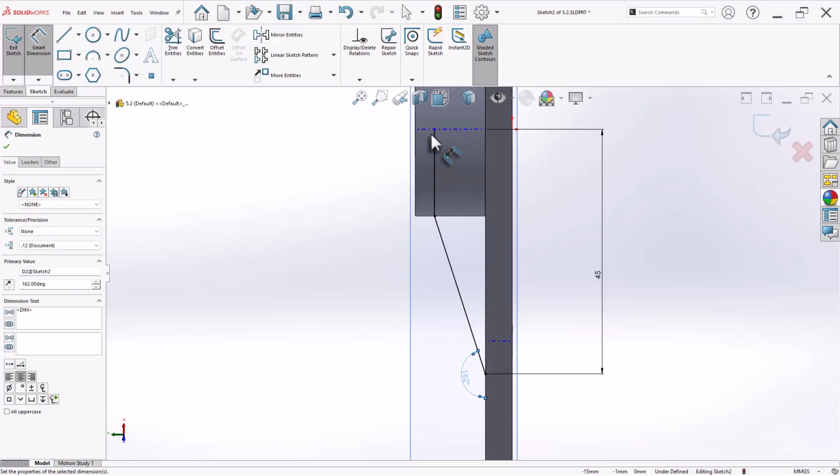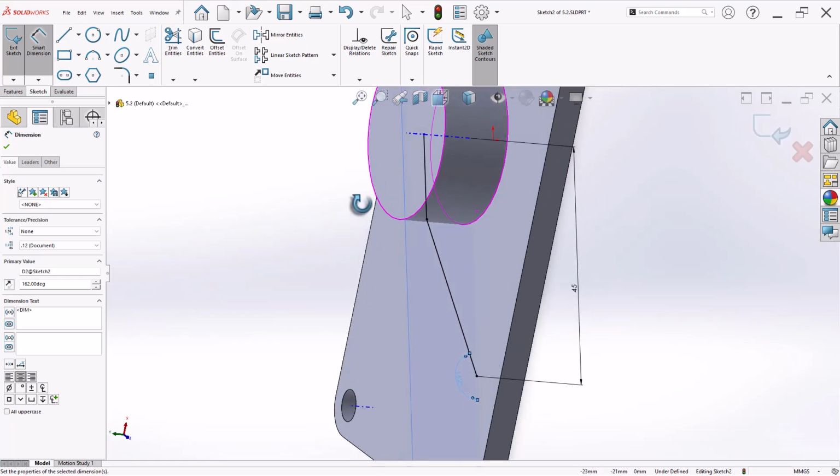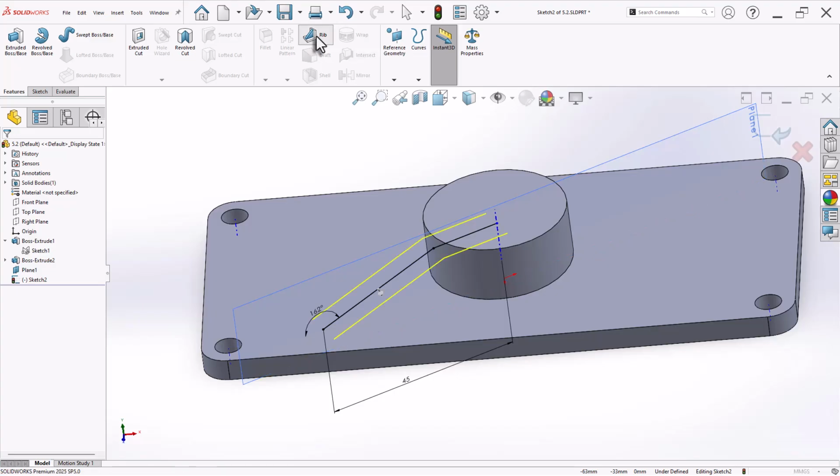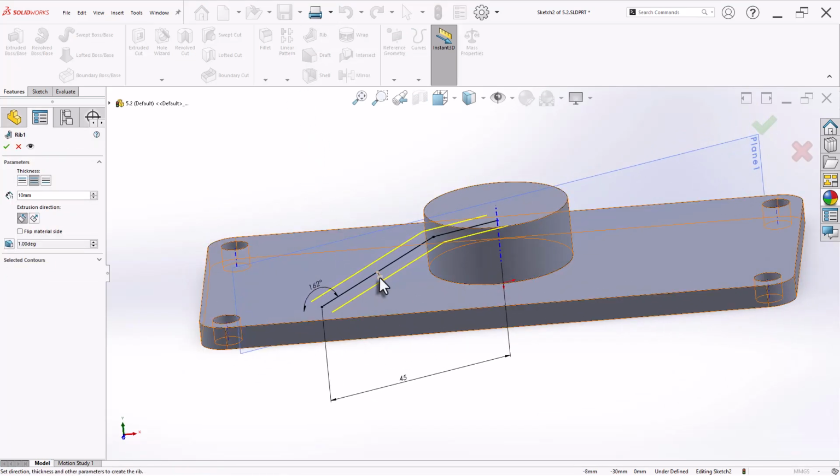It is not necessary to extend the rib up to the center axis. You can extend it by at least 0.5 or 1 millimeter. The material which is going to be created over here at this circular portion should simply match the given sketch in the PDF. Now let's click on the rib feature. This small arrow is pointing downward, which means it is going to add material in this direction, which is correct. It has also selected mid plane thickness, meaning the thickness will be across the middle point. The thickness is given as 9, and click OK.